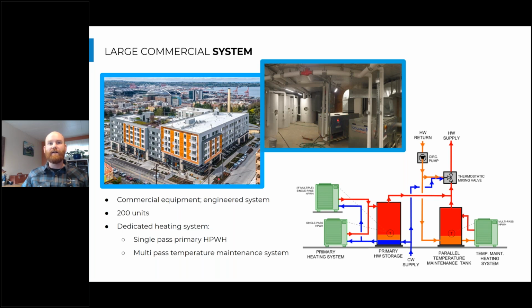But we have essentially 2 primary heat pump water heaters here, coupled to a bunch of storage tanks, and then a dedicated heat pump to do the temperature maintenance heating system. We're going to briefly touch on the temperature maintenance today, but really this is a system that has a pretty substantial impact on a commercial heat pump water heating system as a whole.